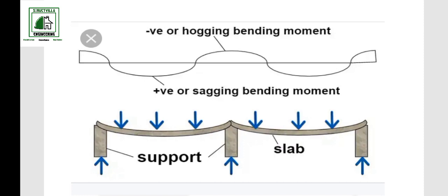So towards the support, the moment there is zero. Towards the mid span again, the moment is zero. Towards the farmost right, the moment too is zero for bottom bars. So that is why we introduce lapping at those points where the moment is zero, which is the leftmost side, the midpoint, and then the rightmost side.